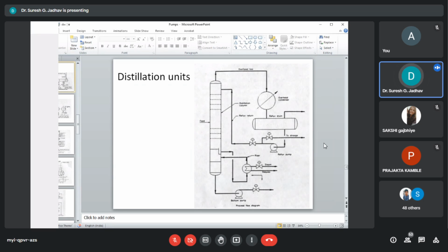In large diameter towers, U-type nozzles are inserted directly into the liquid space. Two tower nozzles are also used. Helical coils inside the tower can also be used for small duties. So in the distillation columns we can use these kinds of reboiler components, and helical coils inside the tower can be used for small duties.